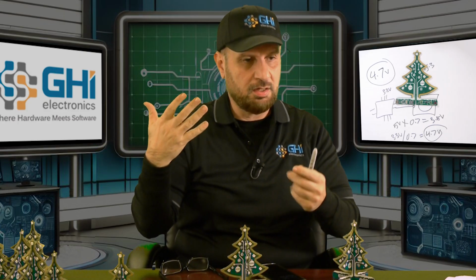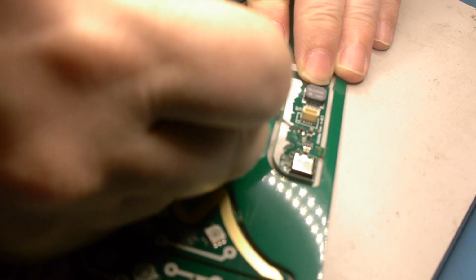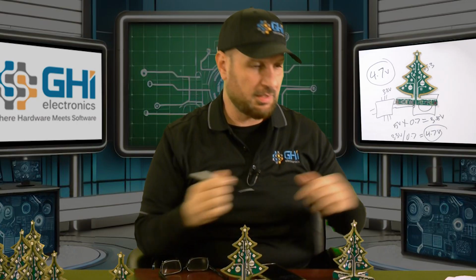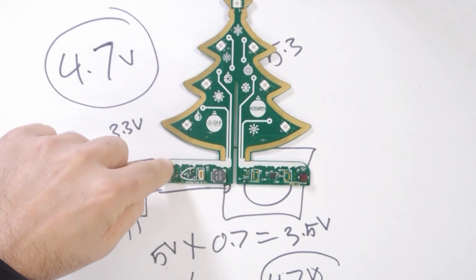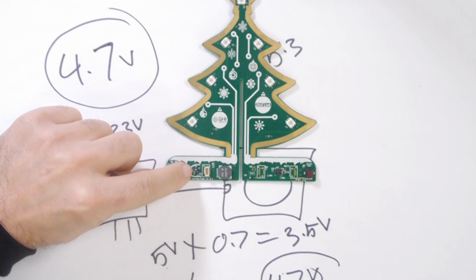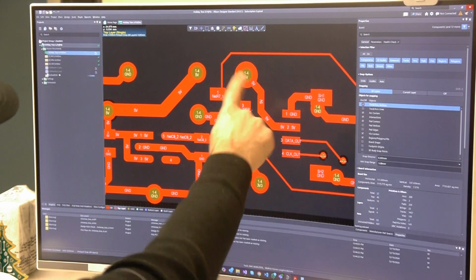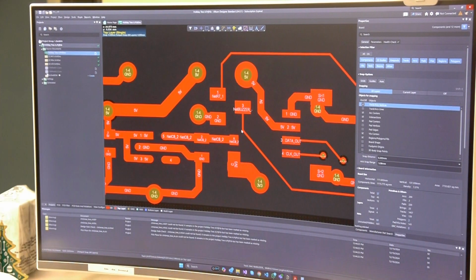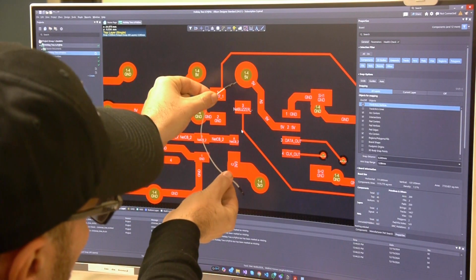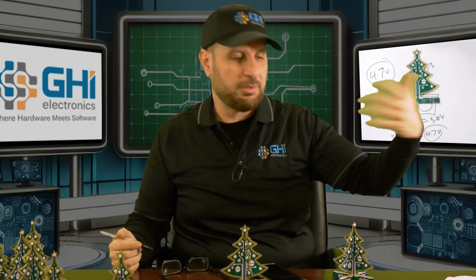Then I got an X-Acto knife and severed the trace, so we cut that trace, and now there's no voltage going to the LEDs anymore. We lost the connection between the 5-volt input and the LEDs. Then looking down here, you see that little wire. Down here, there were 2 vias. One was the 3.3 volts, and one was going to the LEDs. This is after we cut that trace. If we add a little wire between the two, it will bring the 3.3 volts out to the LEDs. So now the LEDs will be powered off 3.3 volts.